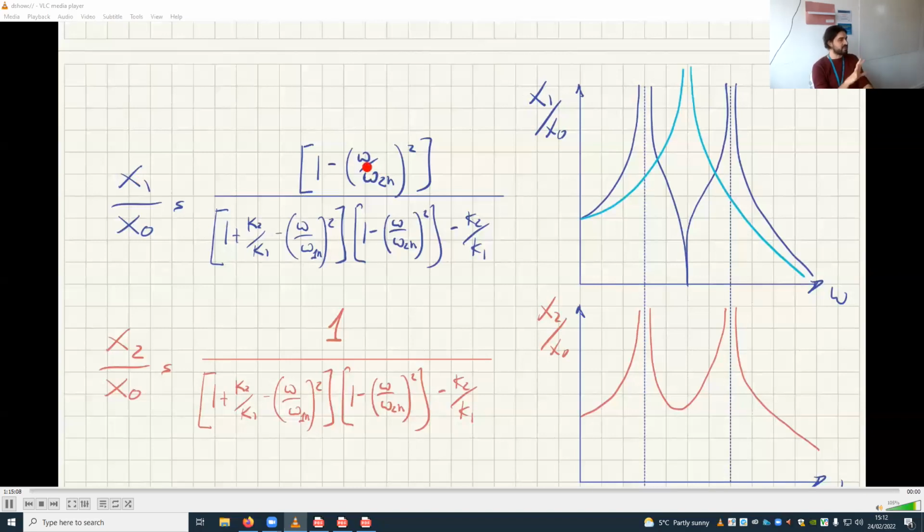So this is the absorbing condition. If it's tuned, the mass doesn't move at all. Now, you can't always make it perfectly tuned, so it will move a little, but a little means in this region, so it still moves much lower than it was moving without the absorber.